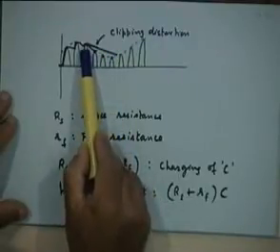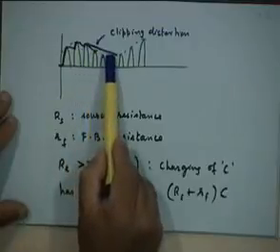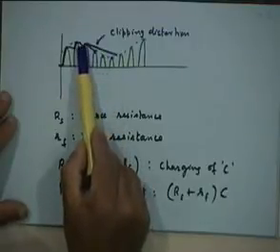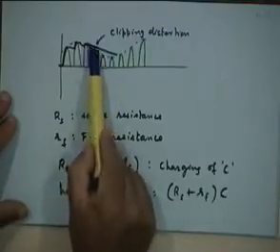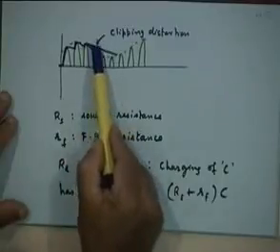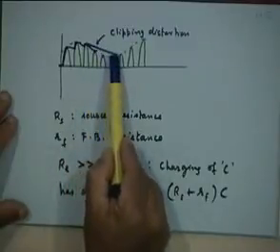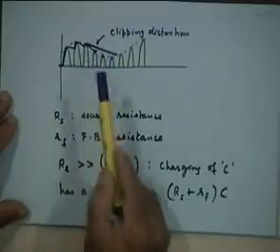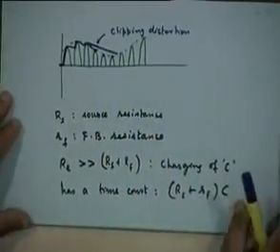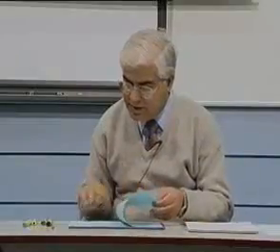You just want to make sure that while the rate of discharge is slow, it is not so slow that you fail to capture the fast fluctuations in the envelope itself, right? So you are comparing this rate of variation with the rate of variation of the message waveform, the envelope. Is that clear? So this carrier frequency does not enter into the picture at this stage.